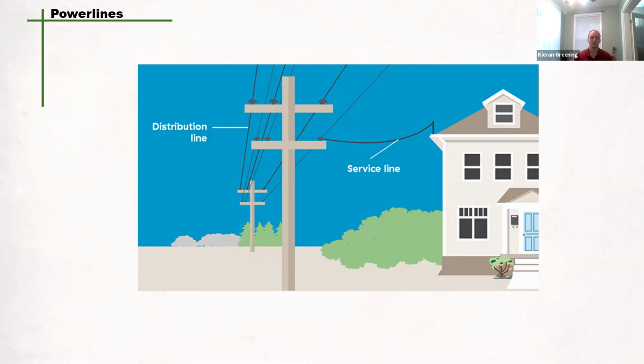It's also worth noting that Sask First Call only does primary lines. So secondary lines run by other people, different services that might not show up with their devices, you'll have to contact a third party to ensure that those lines are also marked before you dig. Because just because it's not a primary line doesn't mean it's not potentially dangerous to your health.